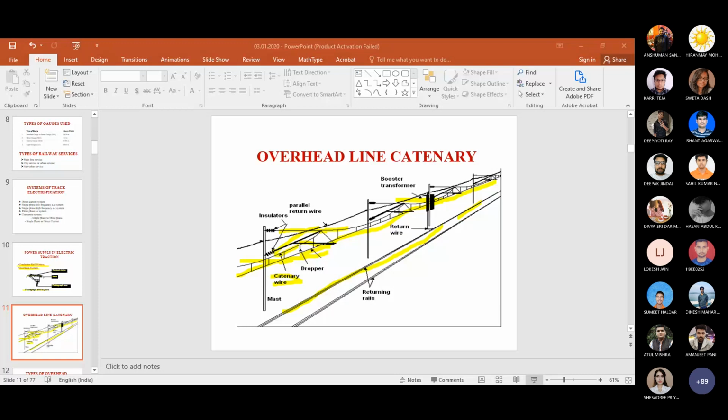Here you can see this is a series motor for the field weakening method. The field winding is connected with the resistor grids. A lot of resistors are connected, and field shunt contactors are there. This is the field winding, and this is the field weakening resistance. All these things are possible and you have to prepare them as per the guideline, whatever values are given. Another thing is the field changer switch.